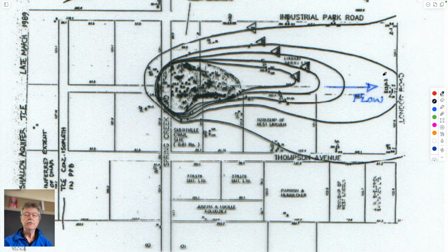To do that, you can't do that just by looking at the site. You need a borehole. I suppose if you had some wells that are drinking water wells and you had steady state elevations in those, you could put together a contour map of the hydraulic water table and project that upstream from where your measurements might be to figure out on which trajectory that problem might exist. So that would be one thing that you might do.